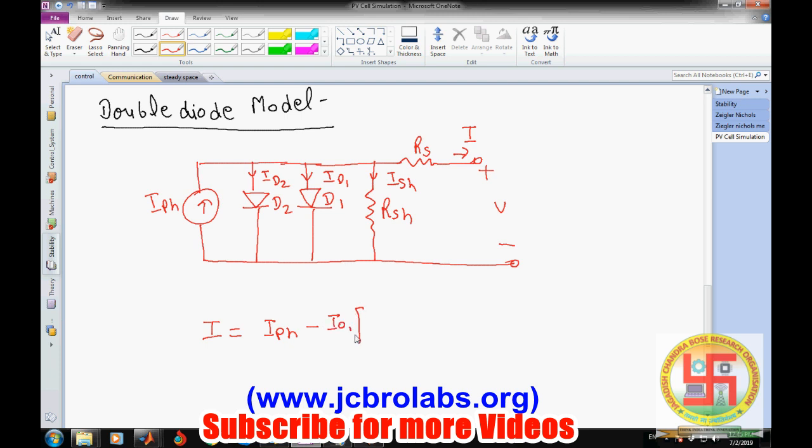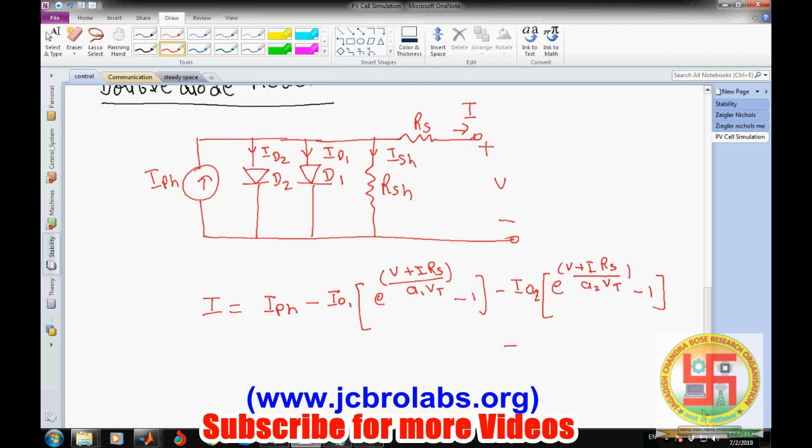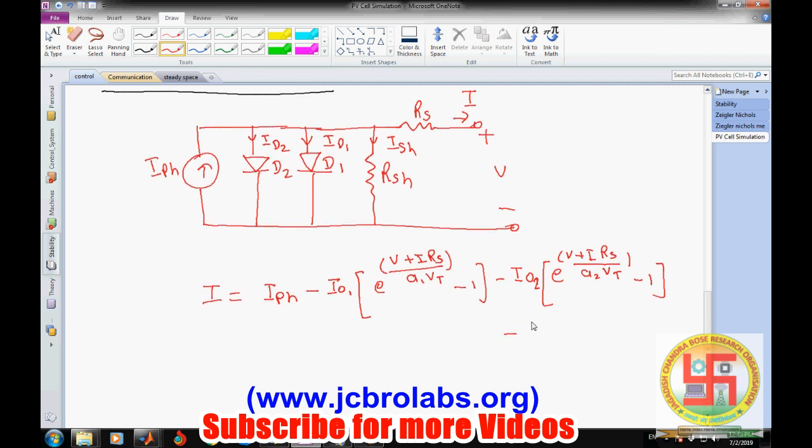So it is IO1 times e to the power V plus I RS divided by A1 times VT, minus 1, and then minus another diode current IO2 times e to the power V plus I RS divided by A2 times VT, minus 1, and then minus this parallel current ISH, which is given by V plus I times RS divided by RSH.